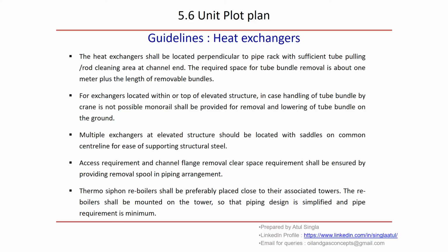Multiple exchangers at an elevated structure should be located with saddles on a common central line. This is just to ease the supporting structural steel. So what we do is provide a common central line for all the saddles.